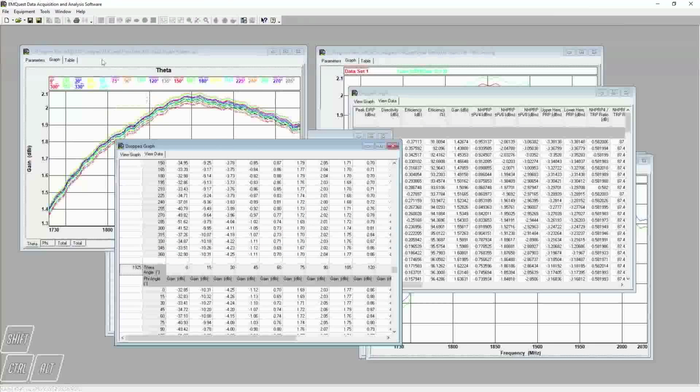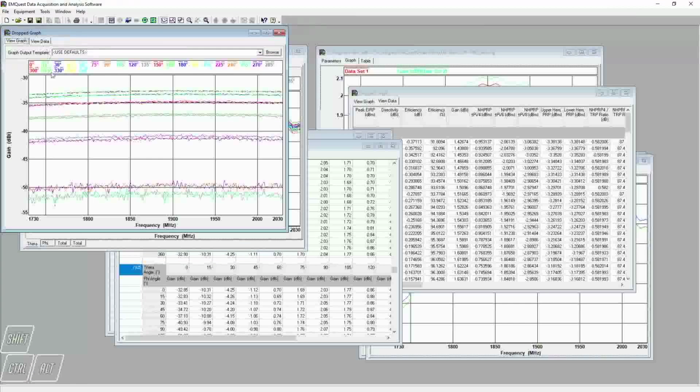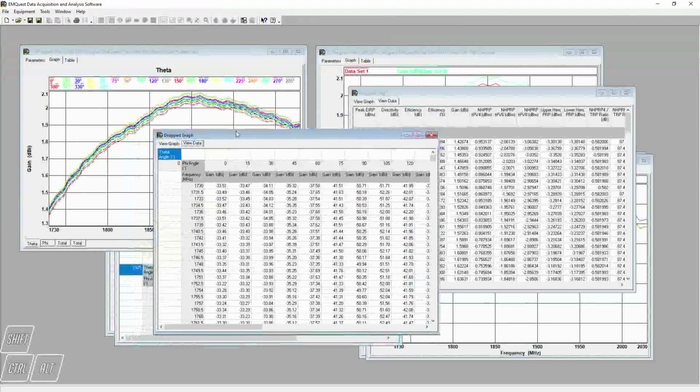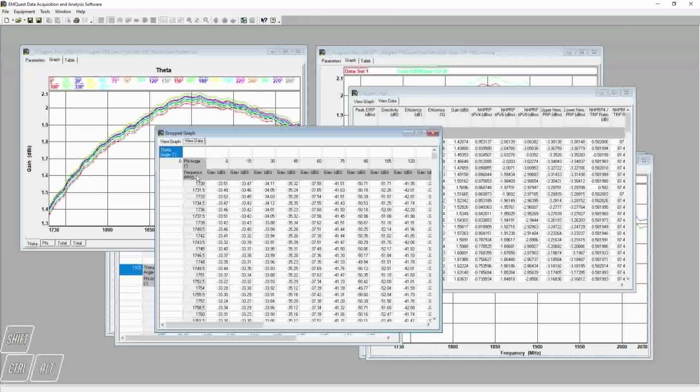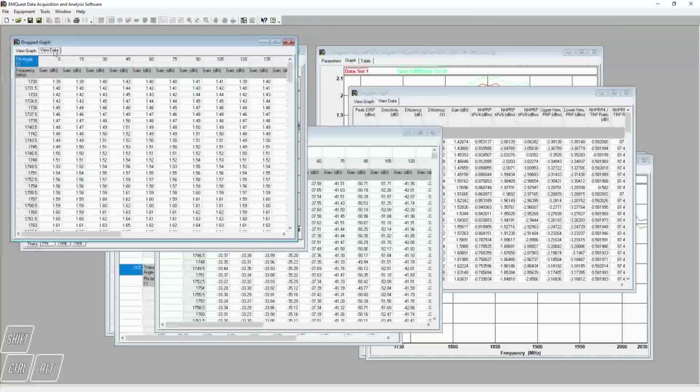You'll notice it doesn't match this formatting. But there's another trick, is that if I hold control and drag, the display changes because it actually changed and copied over matching the format that I had it oriented. So now I actually have the frequency data, and of course if I hold Shift and drag, I get just the graph as it looks, and there I don't have that extra term.